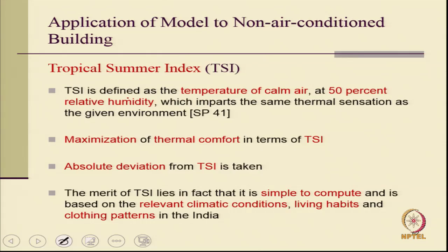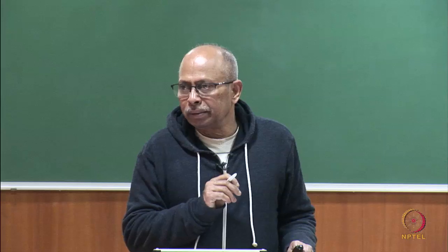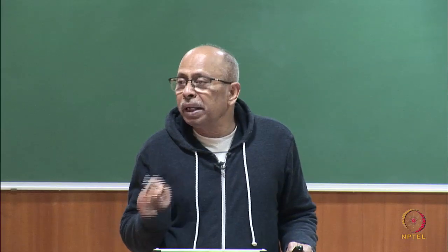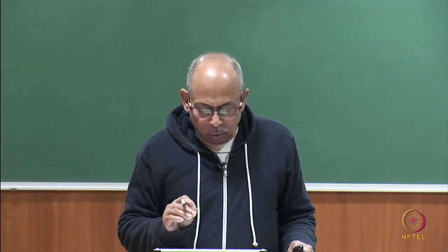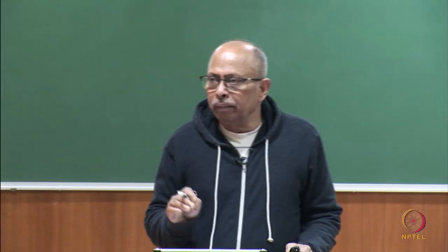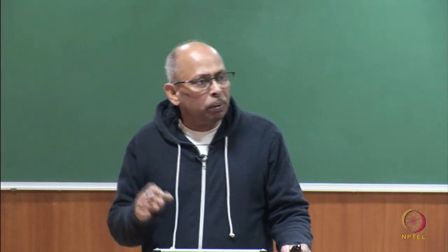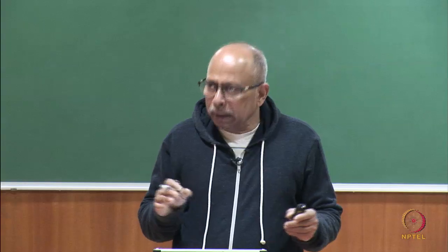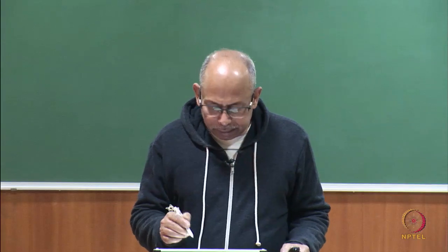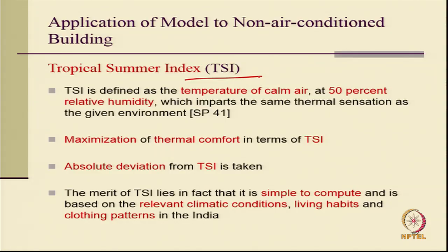Now, for a non-air conditioned building, we do not calculate the cooling load. We calculate what is called some sort of comfort indices. Now, there are various comfort indices. One which is simple and suitable for a country like India, tropical countries, is called the tropical summer index.